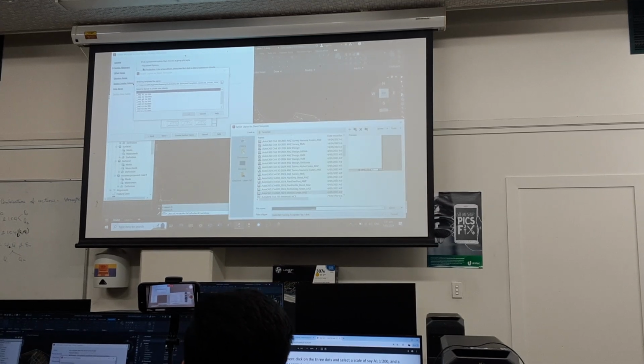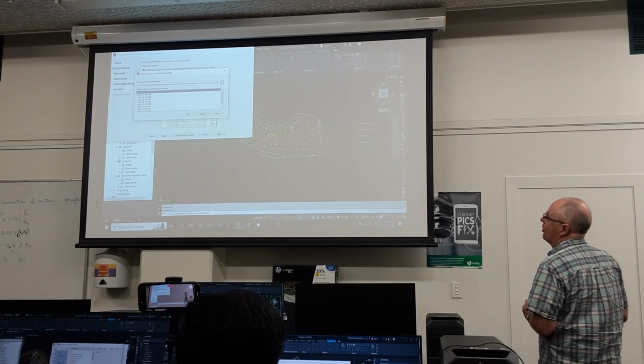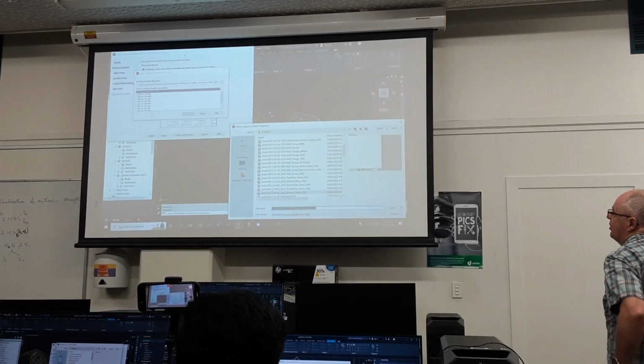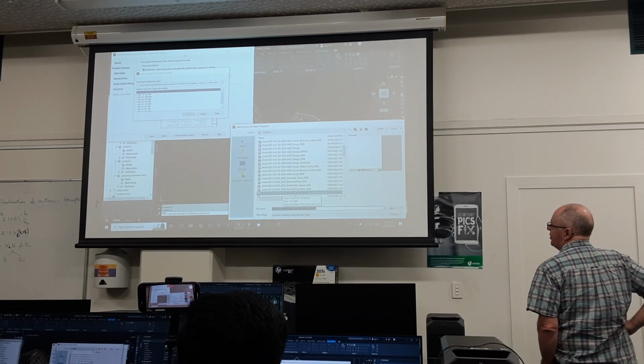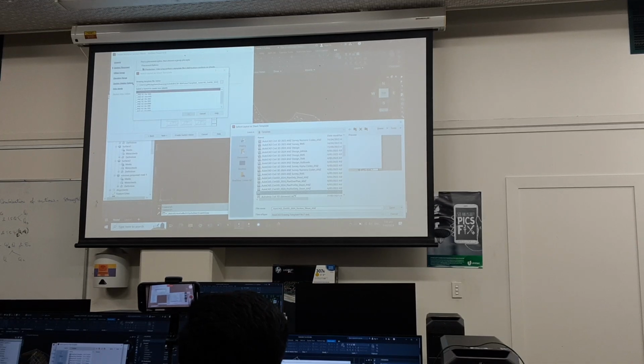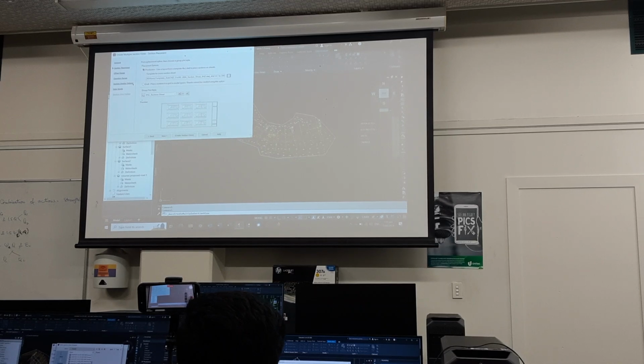There it is there. Yeah, so there's a button missing here, everybody. It's this circle here, the three dots. Hit that, and it pops up the template, and you should have 2024 section sheet, ANZ. So it's already pre-selected, just go open on that, and then go 1 to 200, and go OK. It was actually in there already, and that's it down the bottom there.